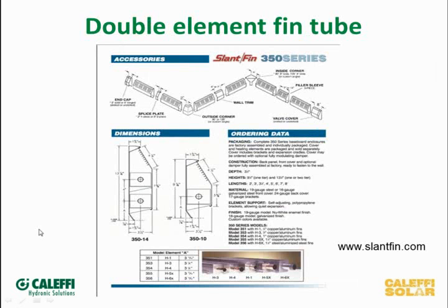Another brand, I know a lot of the hydronic guys in here today will recognize the Slant Fin is probably one of the premier fin tube companies out there. They also offer what they call a double stack system. So what they can do on their larger enclosures is you can put 2 elements in it and stack them one on top of the other. Now that, it doesn't quite double the performance of that, but it really does take it up quite a bit. So if you've got the room and the ability to put a little taller enclosure in there, put a double stack of elements in there, and the same thing happens. You'll be able to either get higher outputs or operate that baseboard at a lower temperature and get similar output.